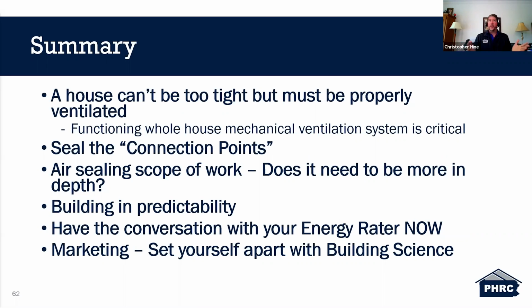Build in predictability. Make sure that in the design phase you're detailing these connection points, so that when you go out to the job site, you have an understanding as to where you may have some air infiltration issues, but you know based on your details that you shouldn't have issues in certain areas. You want to build in that predictability and then hone in on those unpredictable areas. Have the conversation with your energy rater now. Having that up front will definitely pay off and help you in the future, okay? See where you're at, see where you can move forward from.